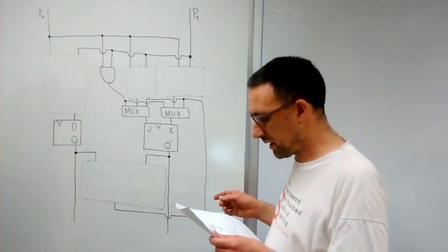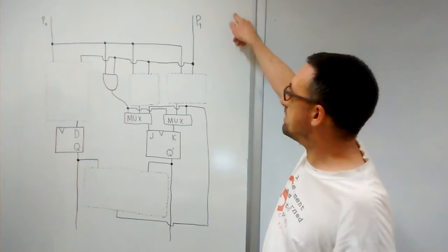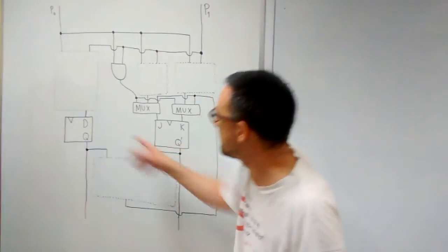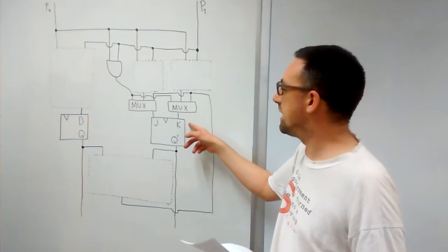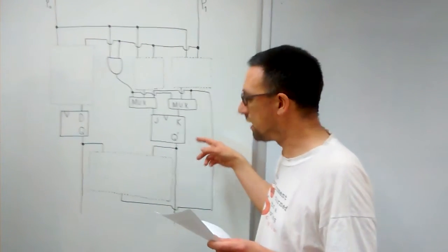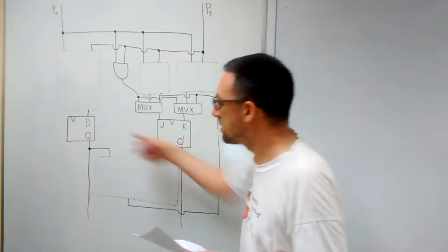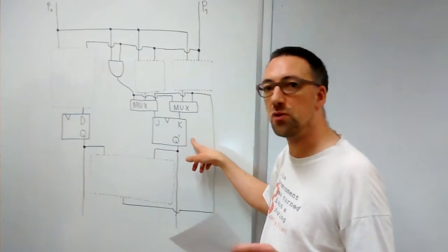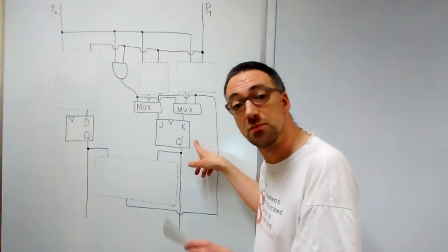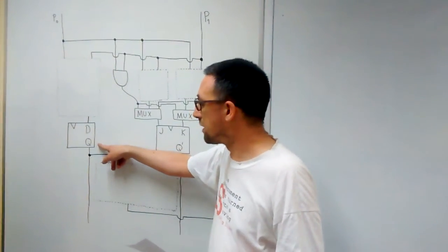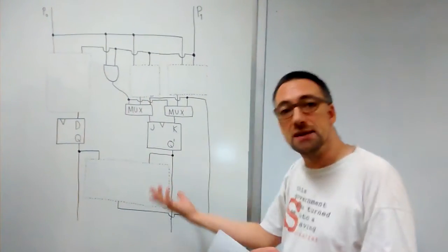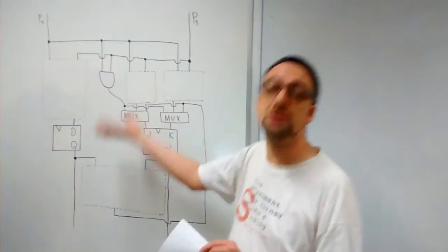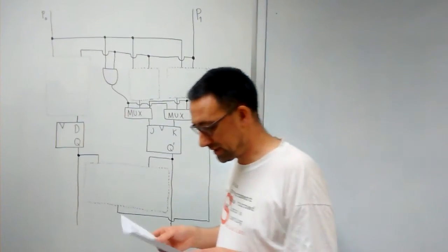We then get told that the machine so far that's been built has these bits and pieces in it. So you can see it's got a D flip-flop with output Q, and a JK flip-flop with output Q prime. And the idea is this: if Q is 0, that means nobody is printing at the moment. But this flip-flop remembered who had the last go with the printer. And if Q is 1, that means that somebody is currently printing, and Q prime will be 0 or 1 according to whether it's computer 0 or computer 1 that's printing.